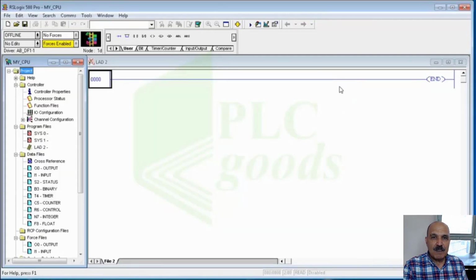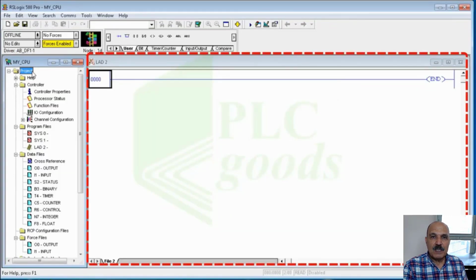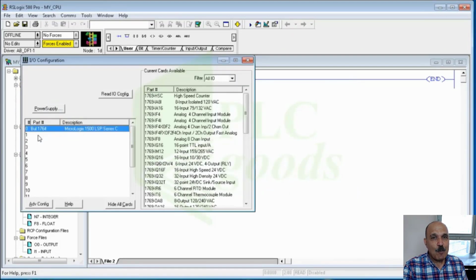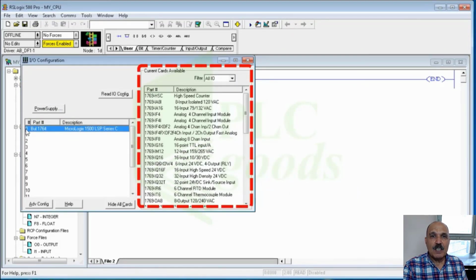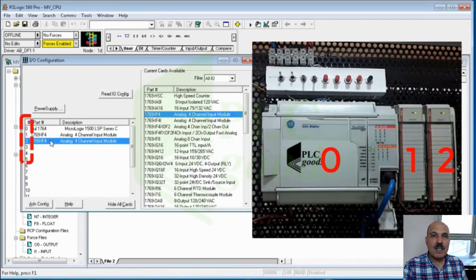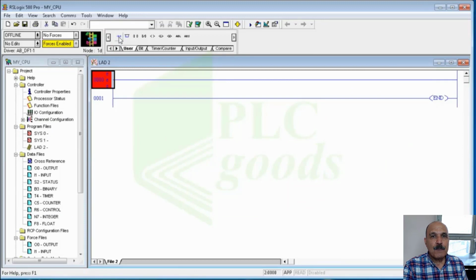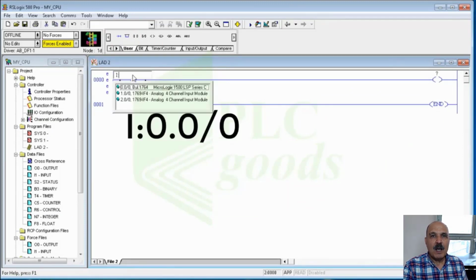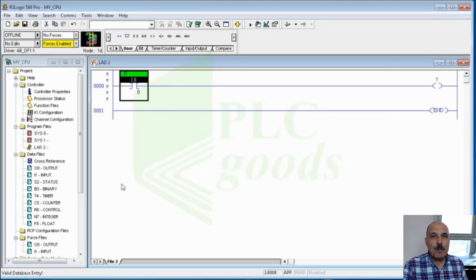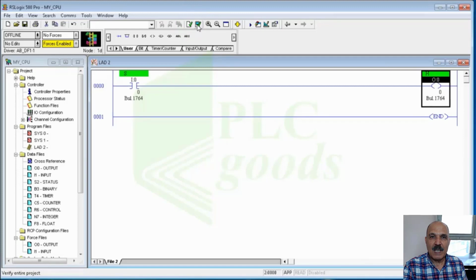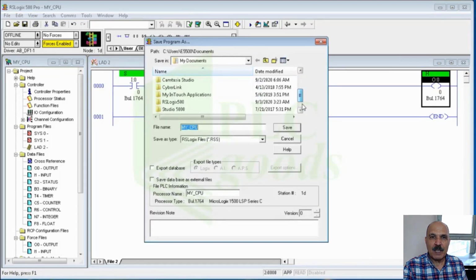writing and transferring a program to the PLC using RSLogix 500, establishing communication between the computer and the PLC using RSLinx, showing how to download and run the program on the PLC. A practical example of how a PLC controls a lamp based on a program.